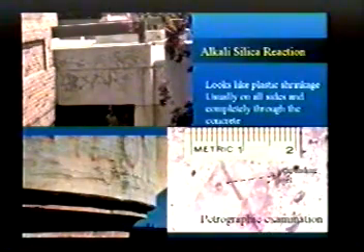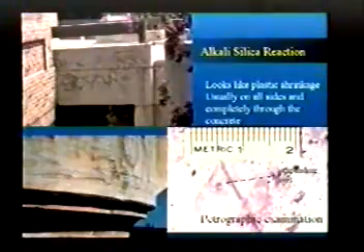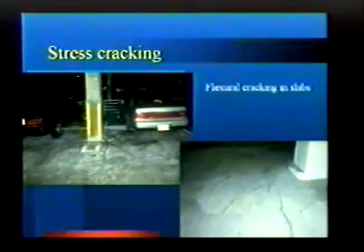Take a look at that crack pattern. That's very similar to one of these crack patterns. Okay, but the source is very different. It's alkali silica reaction. I'm not going to go totally into ASR, but essentially we get a gel that expands inside of the concrete as the concrete gets wet, and it breaks the concrete apart. Okay, this is another picture of it. And again, if you didn't do the testing for ASR, you may not know the source of those two cracks.